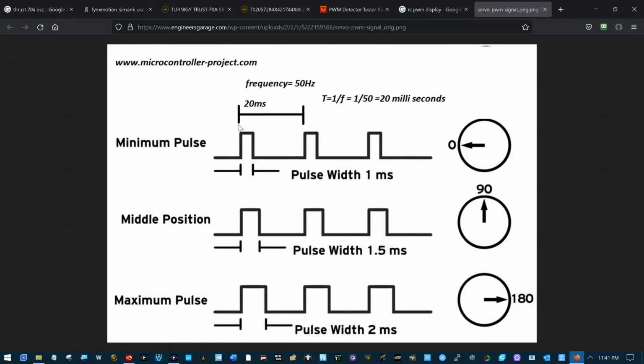and during this time from here to here, when another signal starts again right here, this is the start of one signal. It ends right here at 0. When this comes back up to 5 volts, this starts the second signal. So they're showing 3 signals here instead of just 1. So it comes up from 0 to 5 volts and it stays here for a particular period of time. And this is the width that they're talking about when they say a pulse width modulated signal.